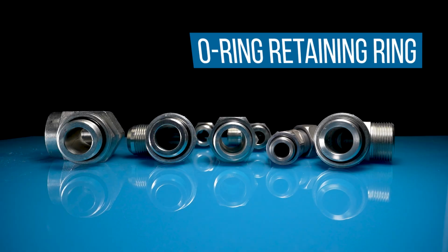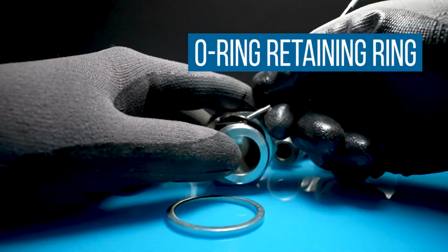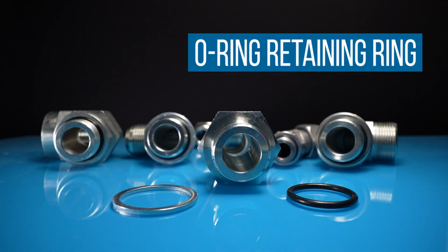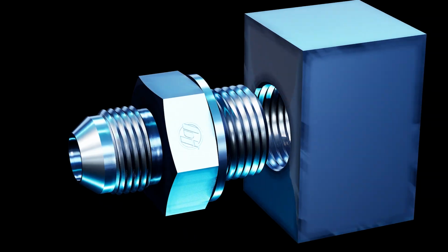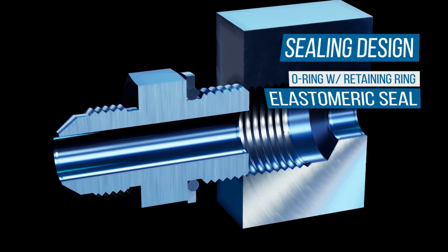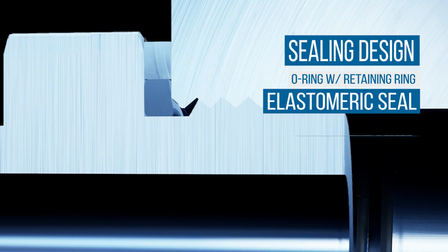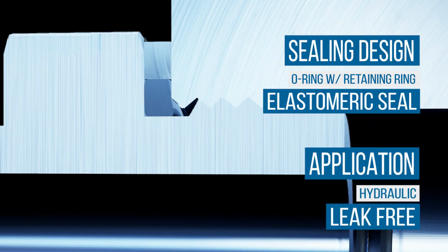Similarly, an O-ring retaining ring, or ORR seal, is an elastomeric seal utilizing an O-ring and a separate metal retaining ring to create the seal. Just like a captive seal, as the connection is tightened, the seal is achieved via the O-ring and maintained by the retaining ring, providing another leak-free connection commonly used in hydraulic applications.